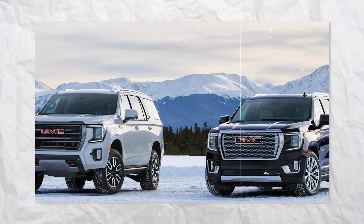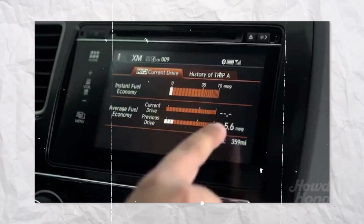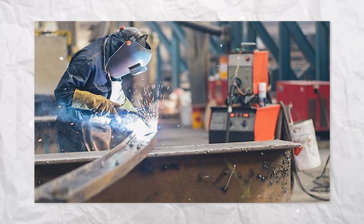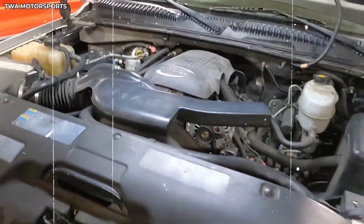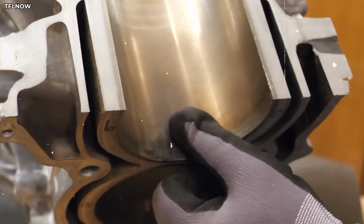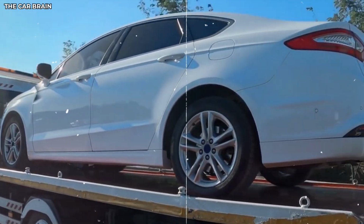The complete throttle response package looks like this. Perform adaptive learning reset, install a fresh air filter or high-flow drop-in, clean the MAF sensor, drive aggressively in sport or tow haul mode for 1 week, then switch to normal mode for everyday driving. This combination delivers the most dramatic improvement in how your Ford responds to throttle inputs.